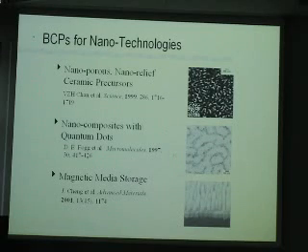During the heat treatment, the organic part is burned out, and then the silicon part actually combined with oxygen, and then convert to silicon dioxide. So finally, they could produce the three-dimensional continuous nanostructure of silicon material, which is the ceramic material. So in this case, using the polymeric material to make the nanoporous ceramic membranes.